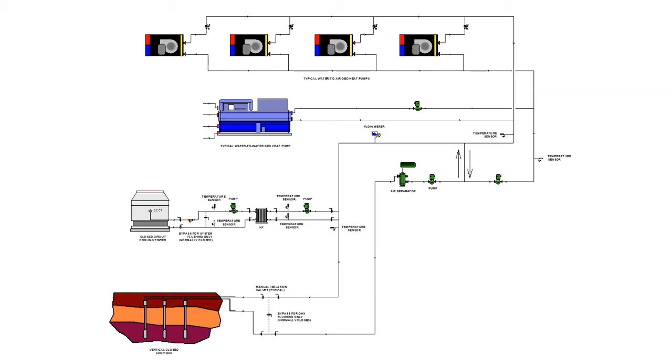In this schematic, the geothermal control system modulates the GHX or geothermal bore field pump to maximize the heat transfer efficiency. It measures the real-time heat flux to and from the bore field, forecasts future bore field temperatures, and then controls the closed-circuit cooling tower to precondition the bore field as needed. Note that this is significantly different from an ASHRAE hybrid approach, where the closed-circuit cooling tower is cycled on a real-time basis to address hot bore field temperatures.